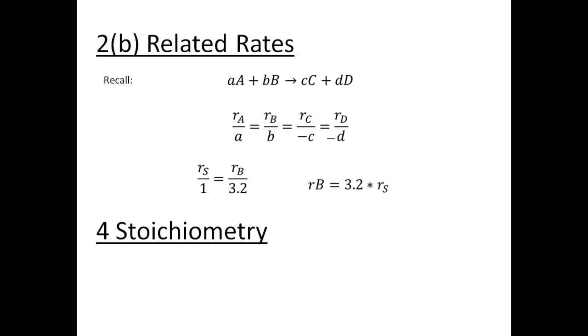The last thing we need to do is stoichiometry. Since our rate laws are in concentration and we are given mass, we need to set up a relationship. Concentration is equal to the total mass divided by the volume and the molecular weight of the species. Using this, we can find the concentration for both styrene and butadiene. At this point, all that is required is a differential equation solver such as Polymath to find the final concentrations.